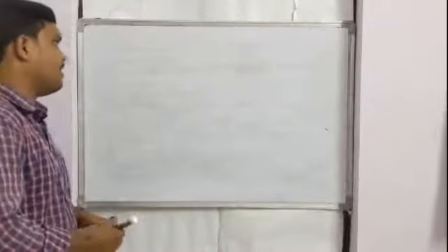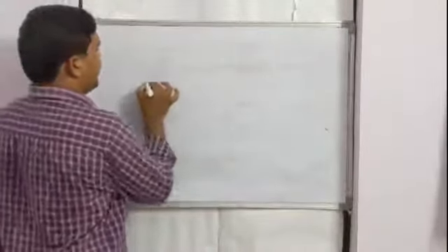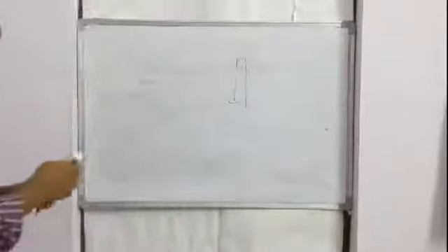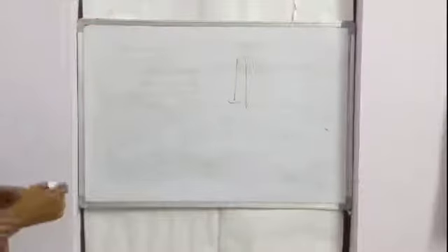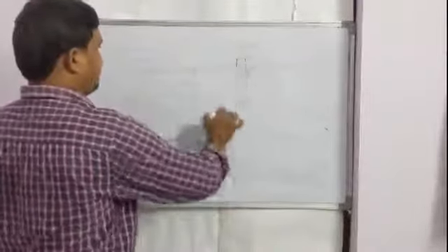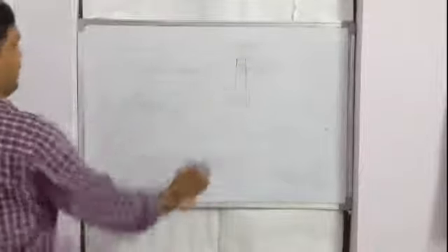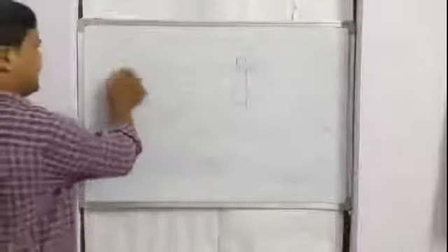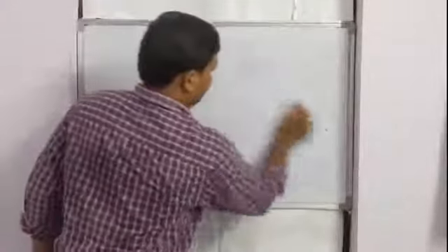And the last one is according to disposition of shaft. The shaft may be horizontal or vertical. Francis and Kaplan reaction turbines mostly have a vertical shaft position, and the Pelton wheel shaft position is always horizontal. So this is the classification of hydraulic turbines.